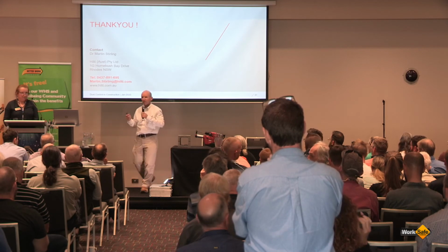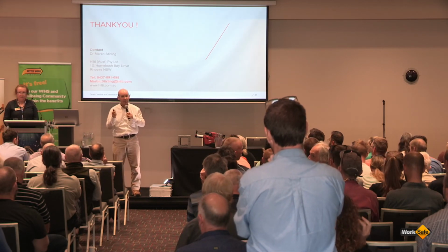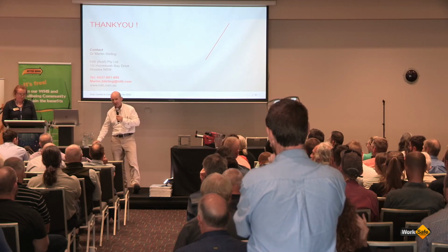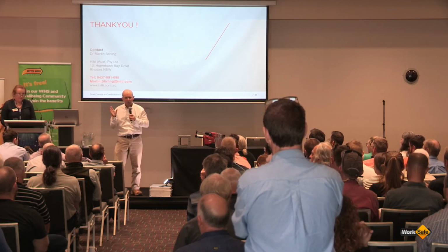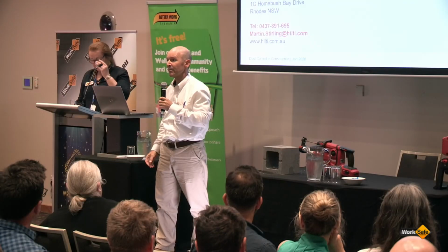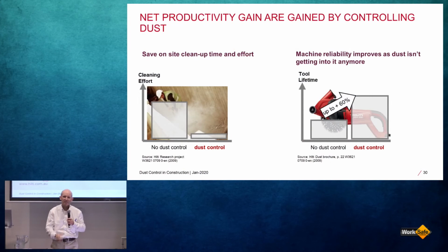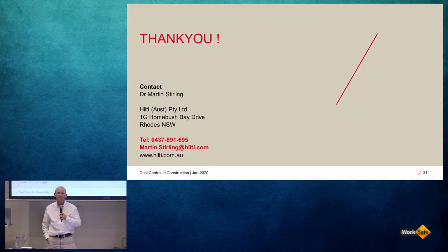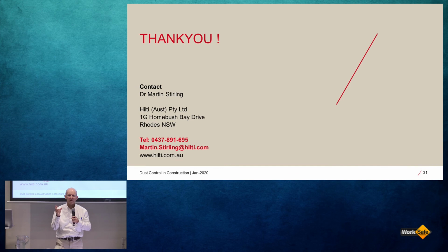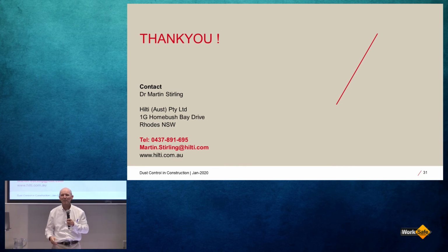So I'm hearing the question, what about the residual dust, like after grinding or after cutting? That's a really good question, and it's about controlling the environment around. What I see a lot of contractors doing now is getting hold of secondary cleaners or air cleaners, which is a further filter. They just look like small aircon units. The likes of Husqvarna sell them, and that does the final cleaning. When I speak to contractors who've been using those types of machines, their workers actually report a better working environment. It smells better, they say, and they feel better, probably because they can breathe better, I'm not sure. But that's another positive thing.